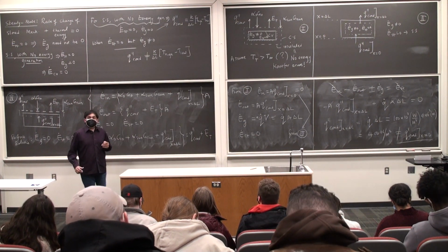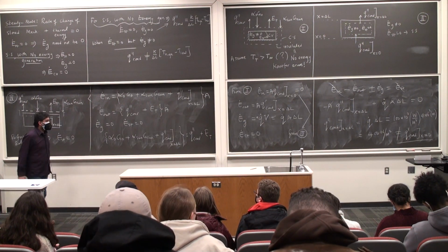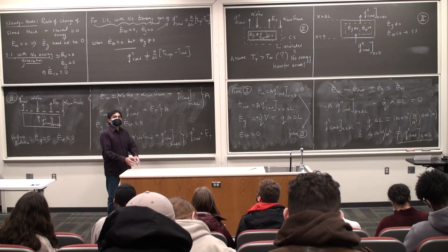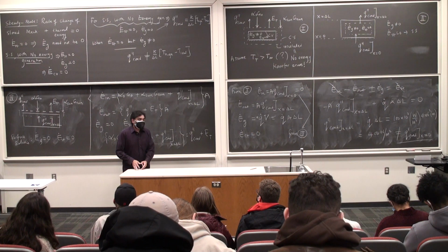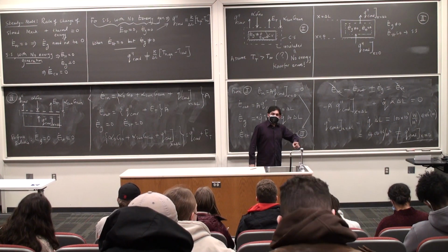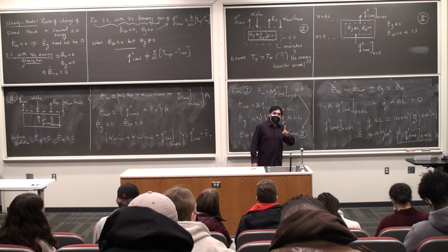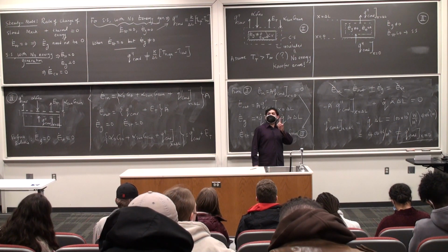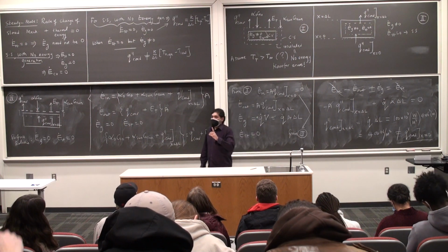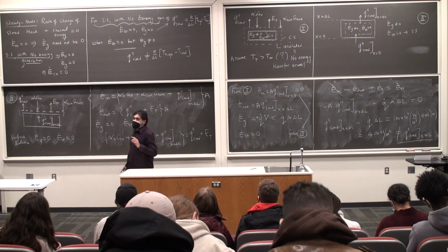And so this example was purposely designed to include generation to prove the point that when I start my lecture on Monday, I cannot assume this very simplistic formula for conductive heat transfer, k by delta L times T high minus T low. That guy is history. You can forget it after the first homework.